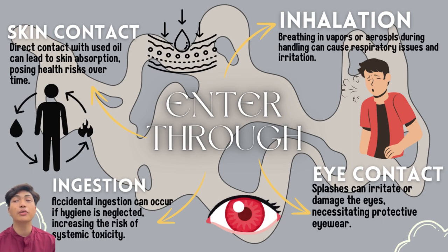The second point is about inhalation. Handling used engine oil in poorly ventilated areas can release harmful vapors and aerosols. Breathing this in can cause respiratory irritation, coughing, and even long-term lung damage. To combat this, we should prioritize good ventilation, use a respirator when necessary, and conduct regular air quality checks to ensure our work environment is safe.